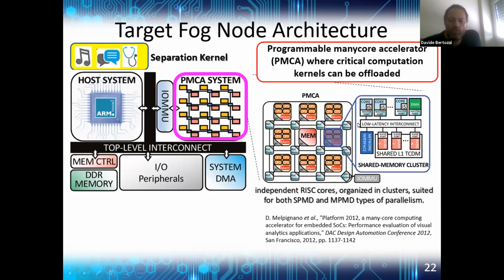When we zoom into a computing cluster, we can see a number of processing cores with their own local instruction caches. And then we have a shared L1 data cache, which is, however, software controlled. Without loss of generality, here we consider this software-controlled, explicitly managed memory. That's why here you have a DMA, and with this DMA, you can bring processing data onto your L1 or onto the L2, and you can process data from there.